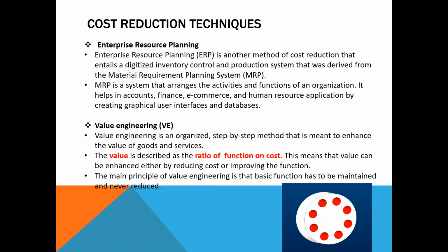So this is nothing but value engineering. How has it been done? Value engineering is an organized step-by-step method meant to enhance the value of goods and services. What is value? Value is nothing but a ratio of function to cost. So if I want to do value engineering, I have to increase the function of the product or decrease the cost of the product. The main principle of value engineering is that the basic function has to be maintained and quality must not be deteriorated or compromised.